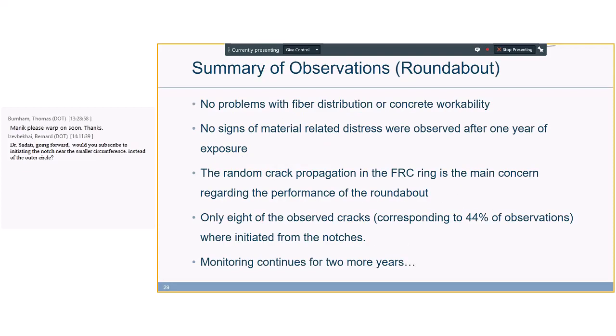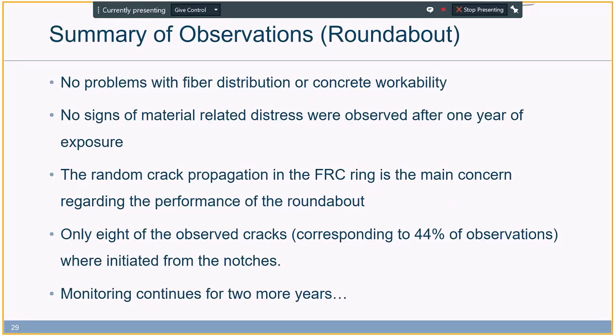So, as a summary, I should say, first, it is a very great experience to be involved in this project. Very nice idea to go with jointless section, but high dosage of structural fiber reinforcement to see the overall long-term performance and cracking behavior. So far, after over 1 year of service, there are no problems with durability of the material. There were no problems with the workability of the material given the 6 pounds per cubic yard of fiber being used. No problems with construction.